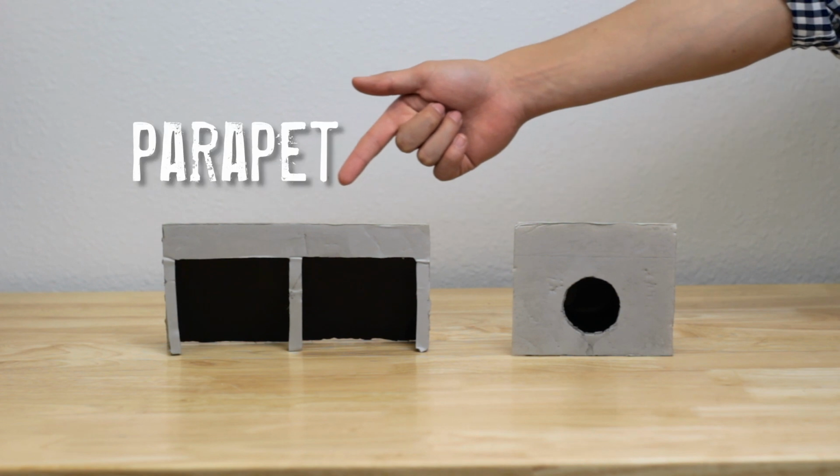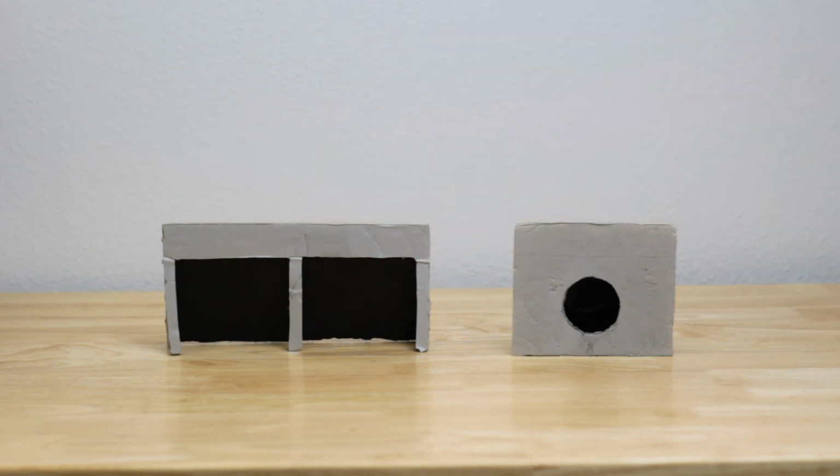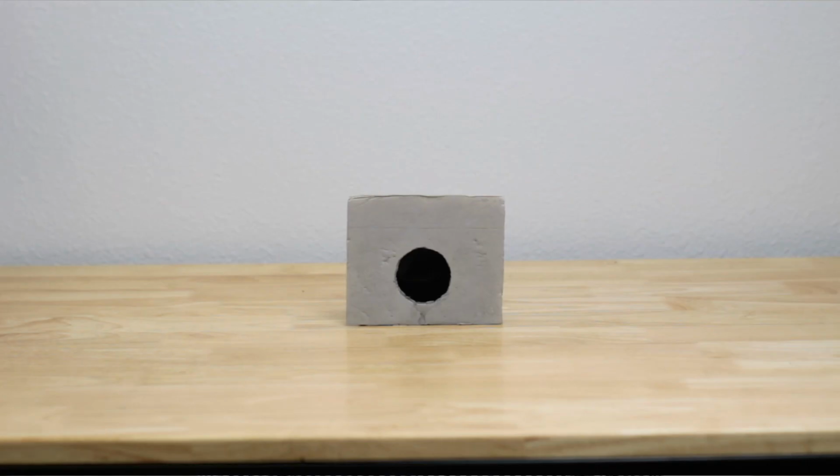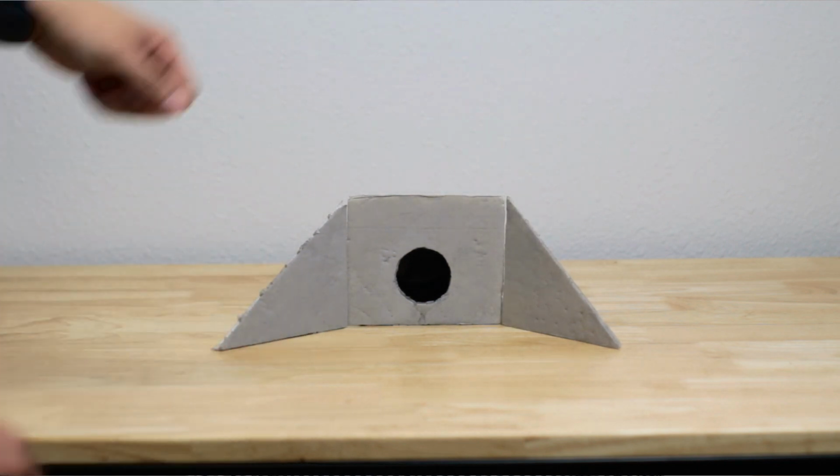Head walls are vertical concrete structures placed at the end of the culvert. This only applies for circular, elliptical, and arch pipes. It shouldn't be confused with the parapet of a concrete box culvert. Sometimes head walls may have wing walls. If that is the case, the end section is a head wall with wing walls.